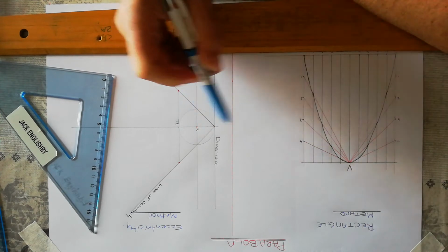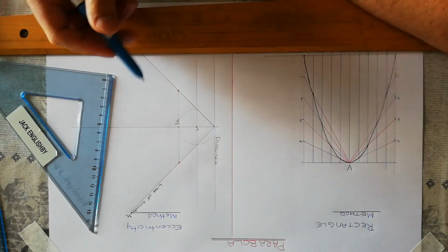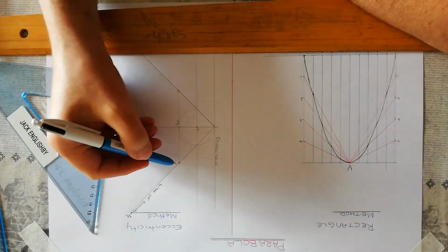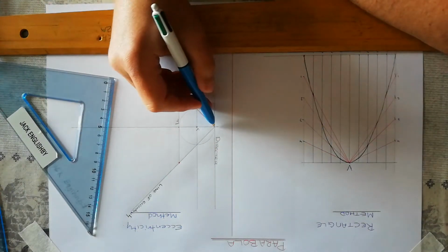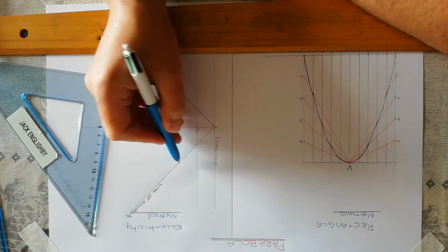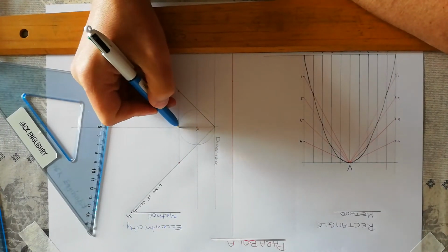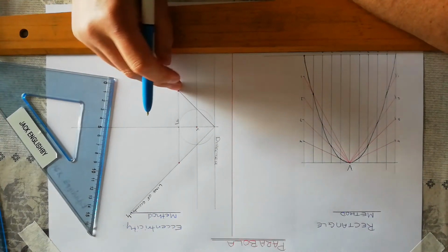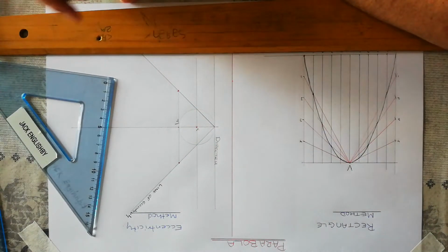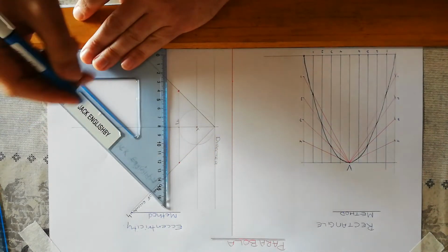We know the V is always going to be a point, the vertex, the top of the parabola. Okay? And the reason we know that these 2 points are definitely going to be points on the curve is because that's 45 degrees. So if I draw a line across, the distance from the directrix to this point will be the same as the distance from the focus to this point. So there are definitely 2 points on the curve. So now we've got 3 points on the curve. Now, for any other point, it doesn't matter what distance it is.